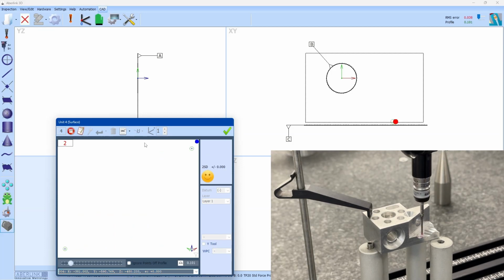And you'll see this will now step 1 millimeter from the start point over to the next point, then work its way to the 3rd point before coming back to the 4th point. So it effectively is just scanning between points. When using contact scanning, i.e. an SP25, it works in the exact same fashion. It will simply try to scan between the contact points that you have selected. So it's looping over to that point and now coming back on itself.